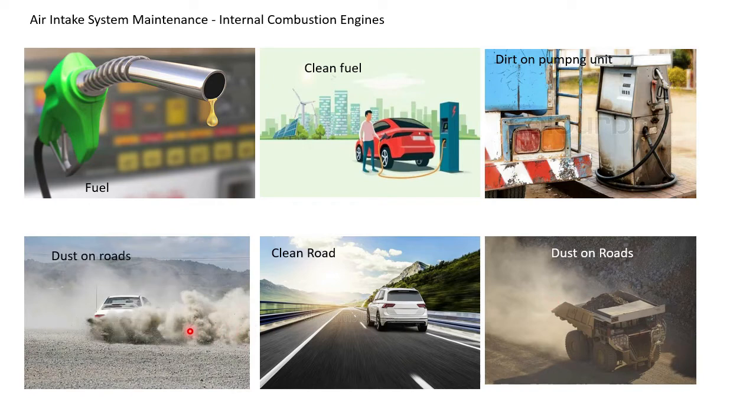Here also, when the fine dust particles which are beyond the filter capacity enter the engine, they mix with the lubricating oil at the valve, valve seats, piston rings, piston, bearings, etc., causing premature wear and tear of the components and also premature overhauling of the engine. So it is essential to pump clean air.